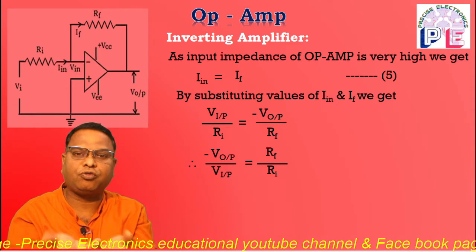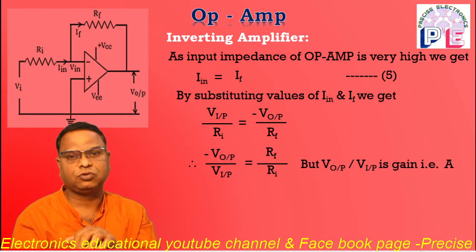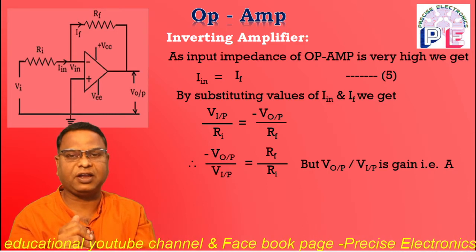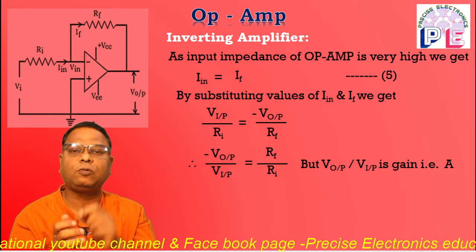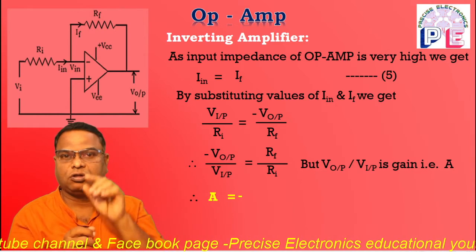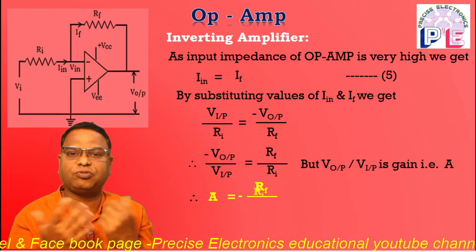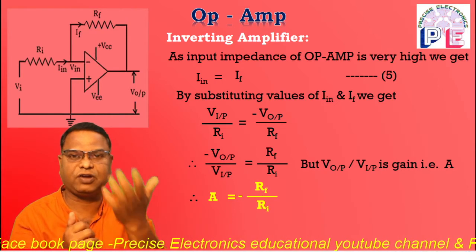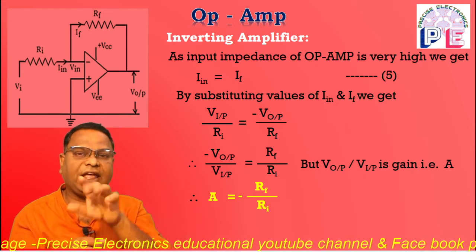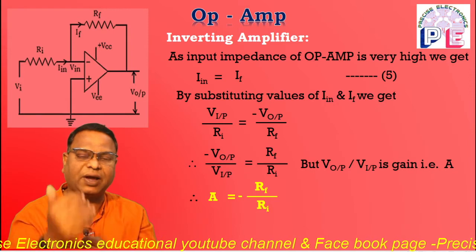What is V output upon V input? It is the ratio of output voltage to input voltage. So that is nothing but the gain. So the gain of the amplifier is given by A is equal to minus RF upon Ri. The minus sign is there, but the values of RF and Ri will not be negative. RF is the feedback resistor, Ri is the input resistor. Then where did the negative sign come from? Because the gain A came out negative, because V output is negative.